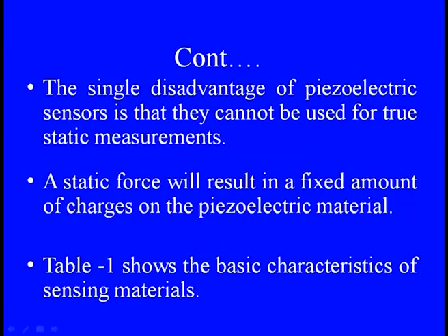But one of the disadvantages of these piezoelectric sensors is that they cannot be used for true static measurement, because a static force will result in a fixed amount of charges on the piezoelectric material. So that is one of the drawbacks whenever we go for static measurement. Whatever the oscillation features are with the charges, they are not showing a clear variation.